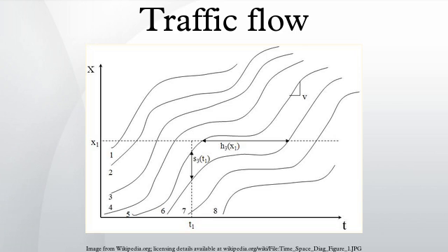There are common spatio-temporal empirical features of traffic congestion that are qualitatively the same for different highways in different countries measured during years of the traffic observations. Some of these common features of traffic congestion define synchronized flow and wide-moving jam traffic phases of congested traffic in Kerner's three-phase traffic theory of traffic flow.